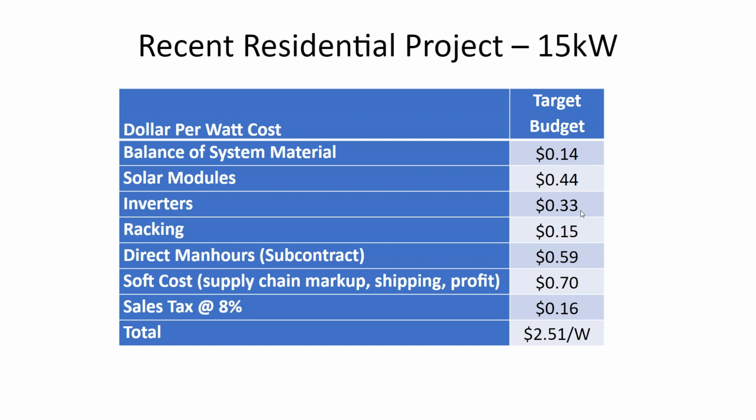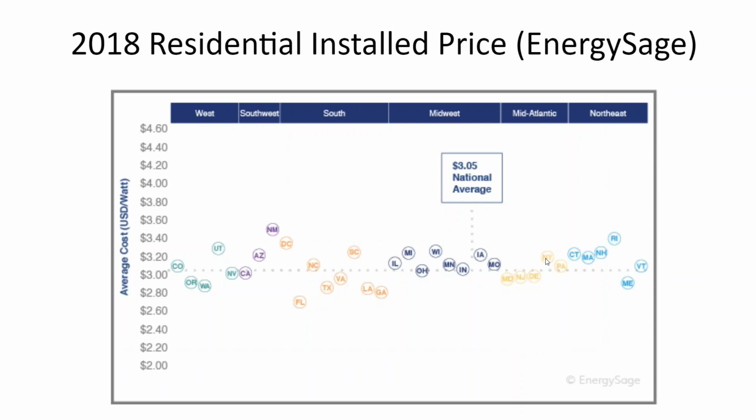And there are some tricks to achieving a good solar project bid from a good contractor who knows what they're doing at this price range. Going through a competitive bid process helps. Doing the preliminary design work helps substantially. And another trick that I do is I buy by the pallet. So it's about 7.5 kilowatts of solar panels per pallet. So I'll commonly bid at the 7.5 kW range or the 15 kW range or the 21 kW range, because it's easier for a solar contractor to manage pallets of panels rather than one-offs.